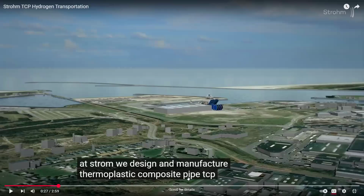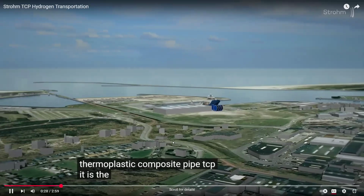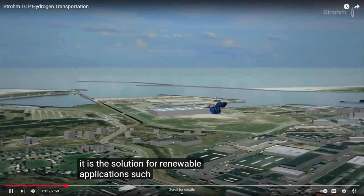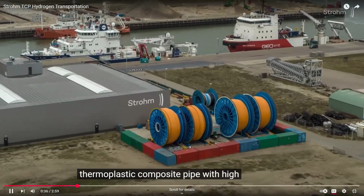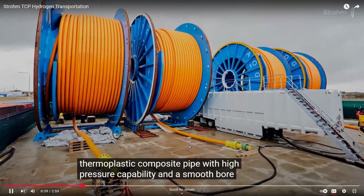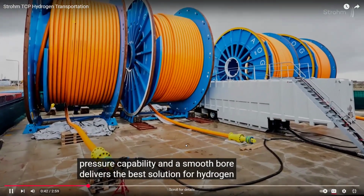As I just mentioned, there is embrittlement due to hydrogen gas in the metal pipe. So metal pipe is not recommended for this gas pipeline system. Plastic composite is much better and much more cost effective. It is the solution to renewable applications such as hydrogen. Thermoplastic composite pipe with high pressure capability and a smooth bore delivers the best solution for hydrogen.